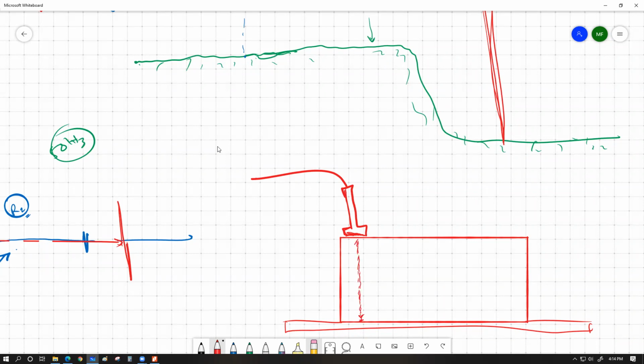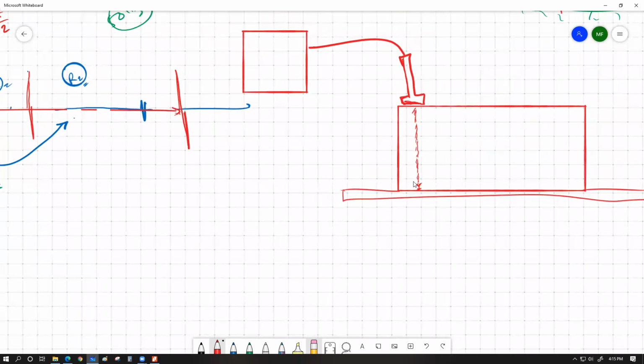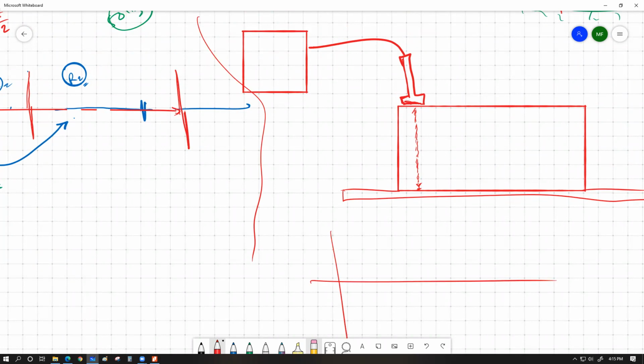And this CRO, with which this probe is connected, would be able to give us the view of that. So if we have no crack within the iron piece, we might get a clean looking reflection graph. Let's say this is our voltage, this is our time.